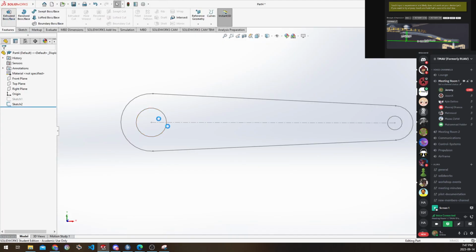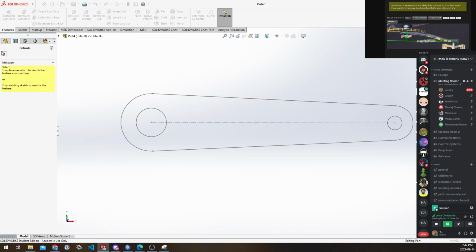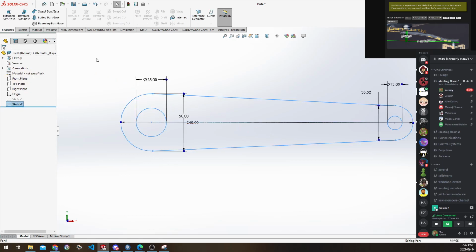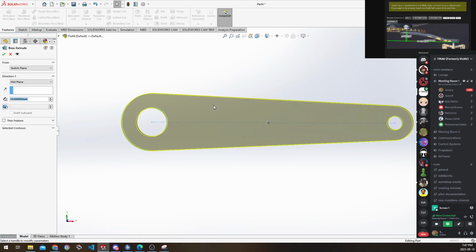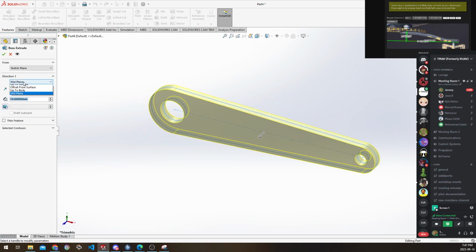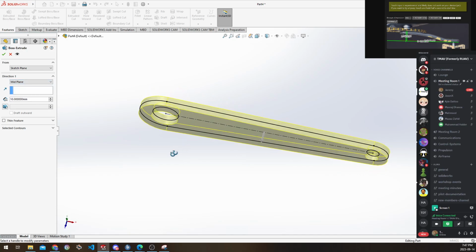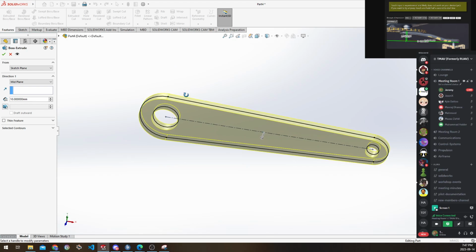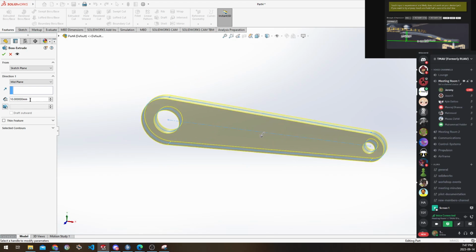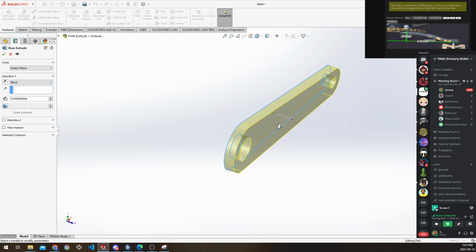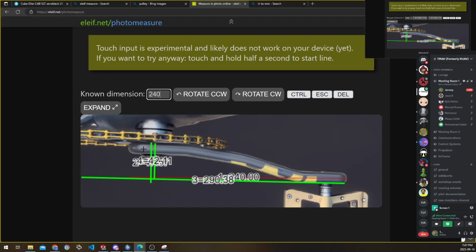So we're going to go and extrude. We're going to select this sketch, Extrude. We're going to do mid-plane because we want to maintain our origin. We want to maintain our origin at that point. So we're going to do mid-plane to keep that in the middle. Actually, sorry. In this case, we want to do blind. The reason we want to do blind is because we're cutting this apart. We want our origin to be right here, if that makes sense.